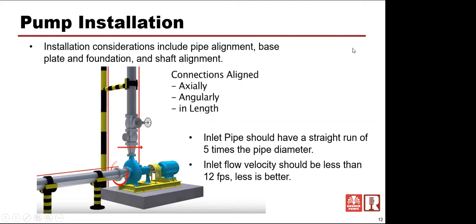And believe me, when you pressurize a pipe that long and you have pressure fluctuations in that pipe, it's going to move. So dynamically, as this thing ran, it was tugging on this pump, causing everything to go in and out of alignment. So again, pipe supports, correct pipe diameters, correct length of straight pipe prior to the suction. The suction is much more important than the discharge side is. And I think that covers a lot of the pipe installation concerns.